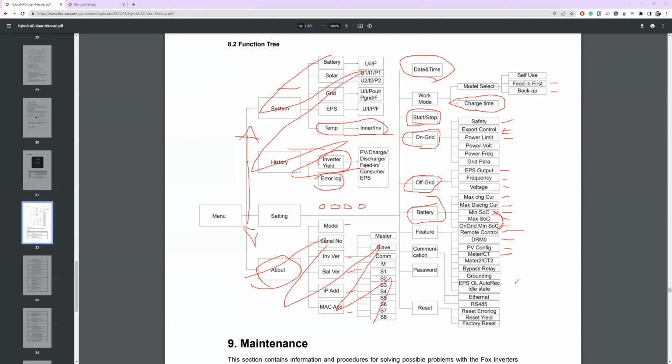It's its only point of information about the energy that your house uses. So it's critical that the CT is positioned in the right location, positioned the right way round, and that the wires are configured in the correct orientation. Sometimes installers will do that backwards, and then you'll have things like the batteries constantly discharging to the grid needlessly. So CT1 is either a CT or a meter that is around your incoming supply.